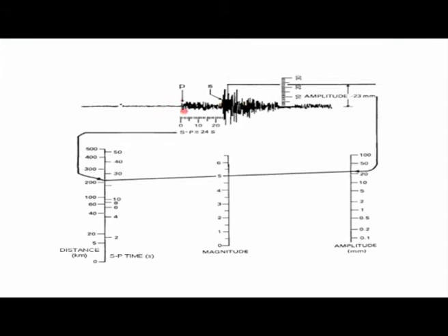S wave next. That means if there is an oscillation, say a pendulum, that one will start vibrating when the P wave comes, and it has a very small amplitude, but when the S wave joins, then it will vibrate more, the amplitude will be more. So we can find out this time, the gap. That means if we can find out the time, immediately we can find out the corresponding distance also.